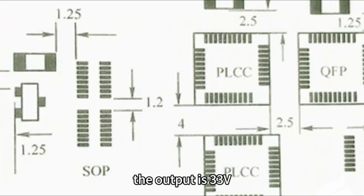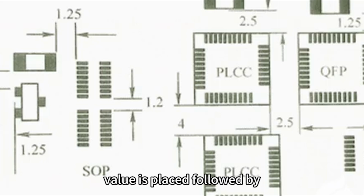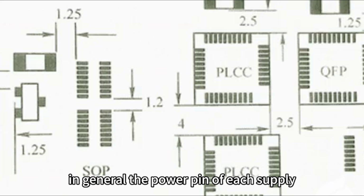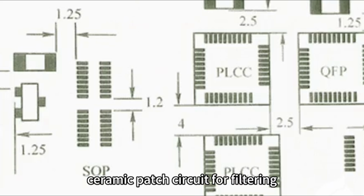The output is 3V, and then the ceramic capacitor with high capacitance value is placed, followed by the ceramic capacitor with low capacitance value. In general, the power pin of each supply chip in the circuit needs to be connected to a 0.1uF ceramic patch capacitor for filtering.